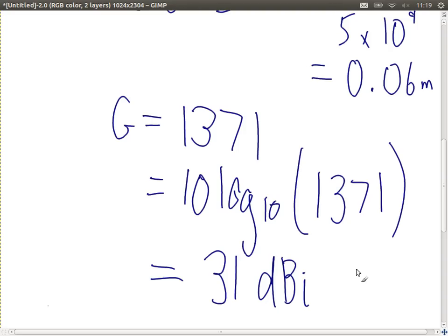Any questions before we move on to the next concept? So when you go out next to buy an antenna, you'll look on the spec and you'll notice which one's stronger based upon the gain, and it will be a part of the spec saying 2 dBi, 5 dBi or whatever. To get more details about where is a signal strong for that particular antenna, you need to look at those plots that show, is it strong in elevation, in azimuth, or which direction.